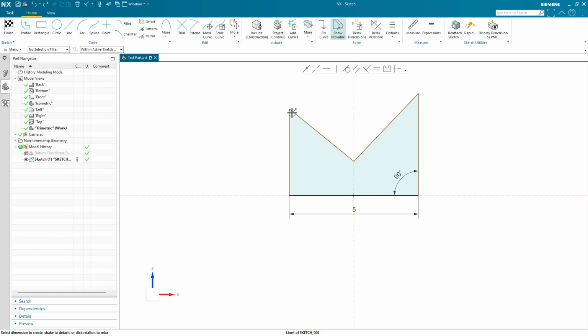But if I come up here, like I grab the intersection of these two brown lines, there is way more play in these. So I can grab this one. I can shrink things down. I don't have to like really shake it to kind of let NX let go of it, so to speak. These are not fully defined lines, and so they're brown. And not fully defined sketches are the enemy in CAD. We always want to fully define everything, because when we take this and we hand it to the manufacturing people and they say, how long is this, or how big is this dimension, you can't just stand there and shrug your shoulders and say, I don't know.